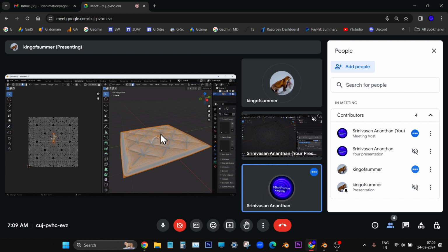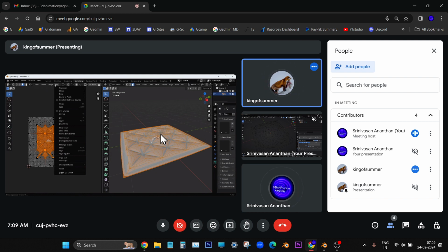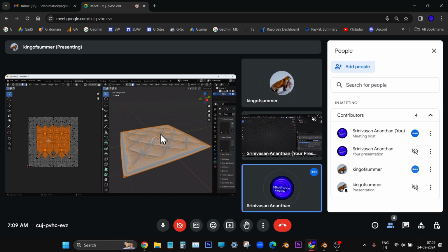It looks different. Using the rectangle selection, just select some faces. Now go to the same UV submenu and apply split selection. Now switch on the face sync button, the one on the left side with the opposing arrows.